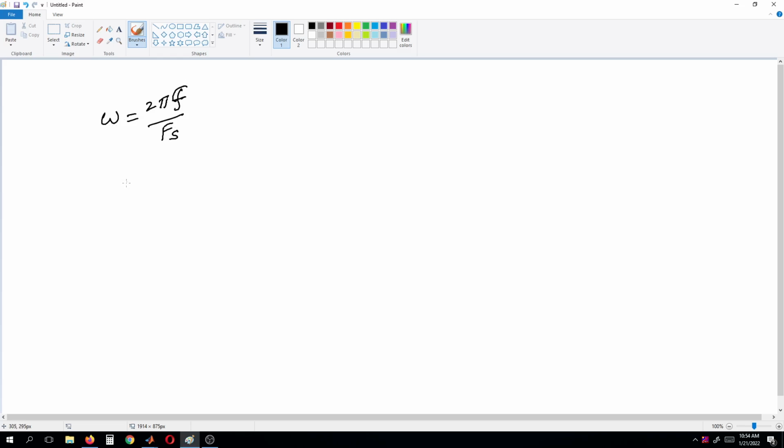If you calculate the FFT, we have 0 to 2 pi radians, and if you do sampling on every second, then omega k is given as 2 pi k upon N. Now we will equate these together and try to find out the frequency for our filters.